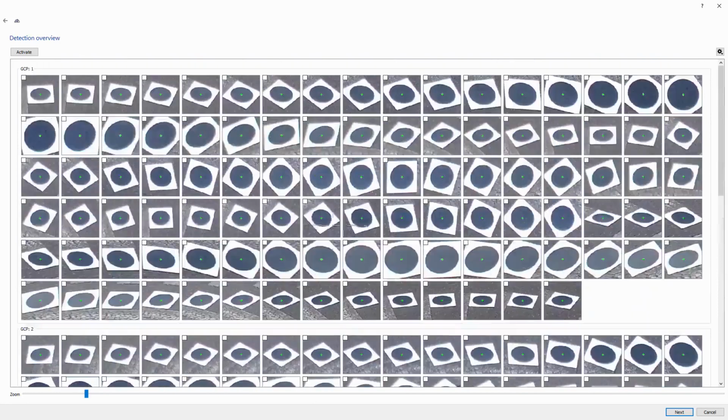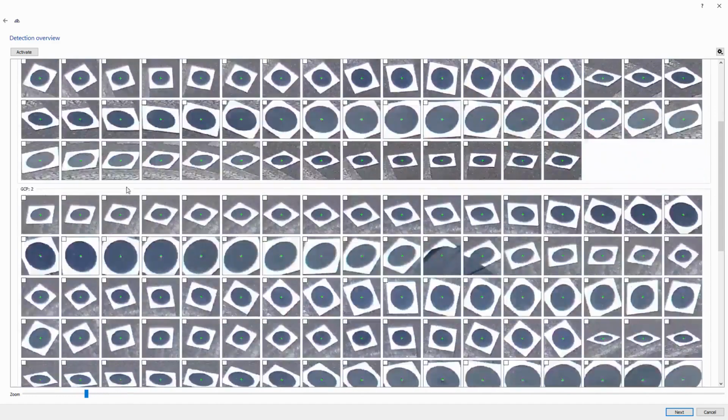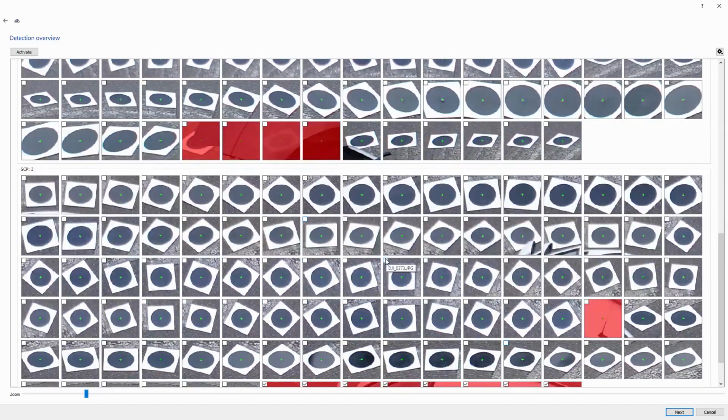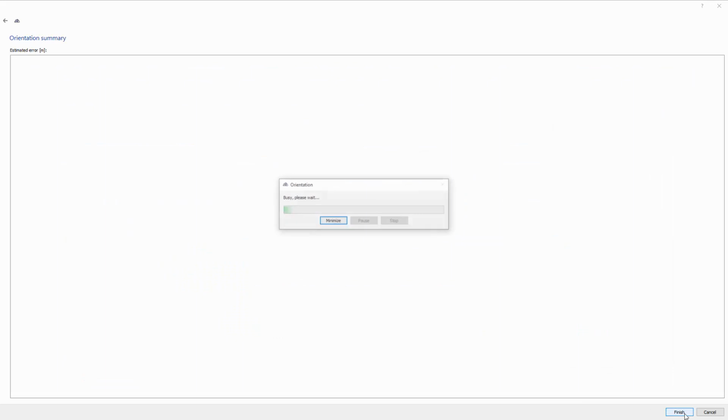And what we can see here is actually ground control point 1 is on, let's say, 50 images, most and all. Ground control point 2 the same, on at least 15 images, and so on. And in this way we orientate all images really accurately. I'm satisfied with this one.